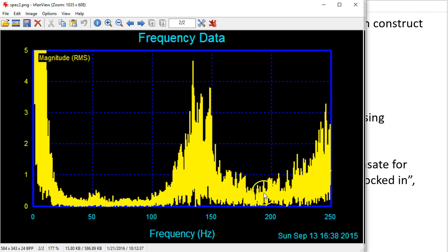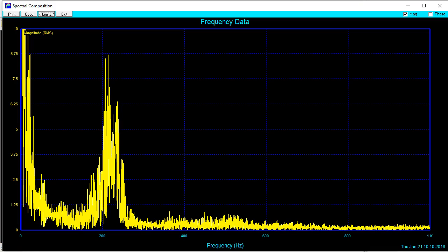But you can see here that there's something going on at 275 and 300 Hertz. What is it? I don't know, but boy, there's a big peak in energy, and we're not seeing it because our sampling rate isn't high enough, and Nyquist-Shannon is cutting us off, but that is still showing up in our data. Now, this is the raw gyro data from